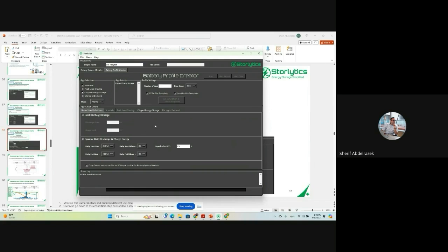I'm going to turn this microgrid app off. We have everything we need to run the simulation, but the run button isn't on. So what we do here, we know that our PV profile is 15-minute resolution, right? Well, no one here knew that. I only knew that. So I know it's 15-minute resolution, but you can know that by opening the CSV file and seeing its resolution. But we know it's 365 days. So we set 365, and for time step, select the 15-minute option. Right? And then set simulation and create templates.